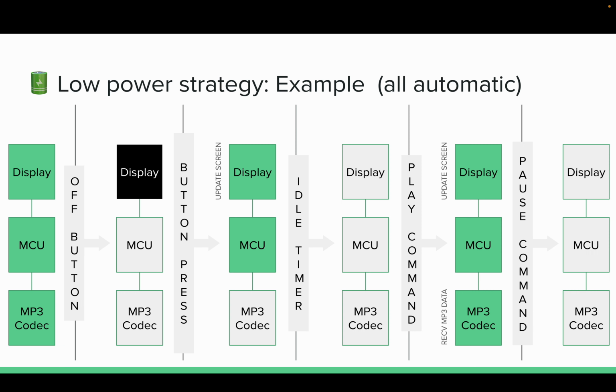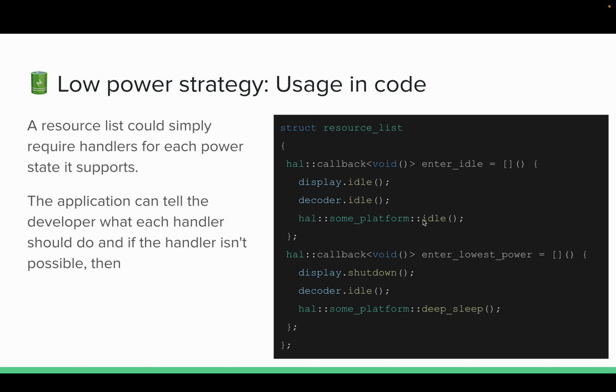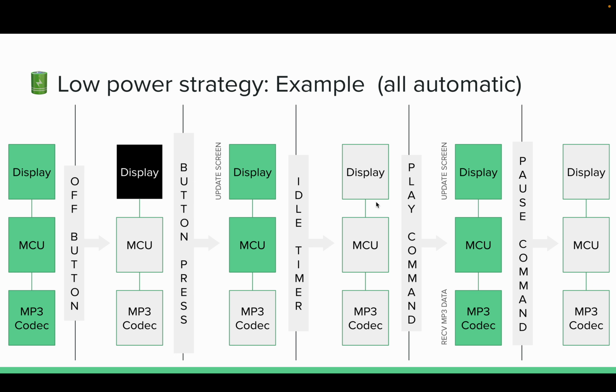The thing I also like about this, kind of looking back at this example, is that if you are spending most of your time in your idle task, and your idle task just puts it to sleep and then waits until something happens. Oh, side note, if you ever use the wait for interrupt, you're going to want to idle everything else first before you idle your platform. Otherwise, you won't be able to get to the other callbacks here because you'll jump out. I could see some weird behavior happening if you were to idle the platform first and then idle your other things.